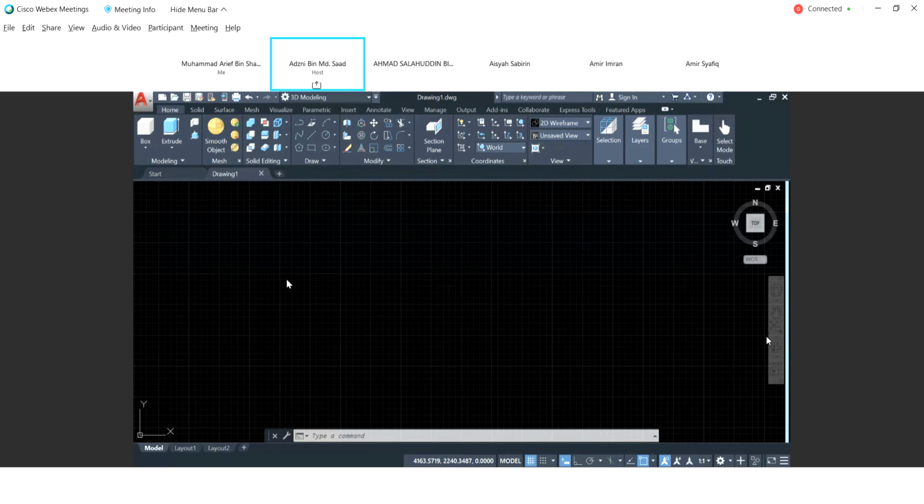For the basic fundamental principle I explained last week, you can construct whatever object based on geometrical 2D drawing. Whatever shape you want to do, you can do it using that approach. But AutoCAD already provides some basic shapes that you can construct directly using this function, in the modeling ribbon up here on the top left-hand side of your AutoCAD interface.